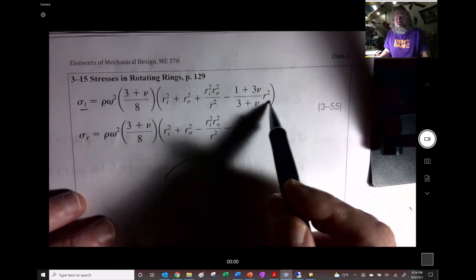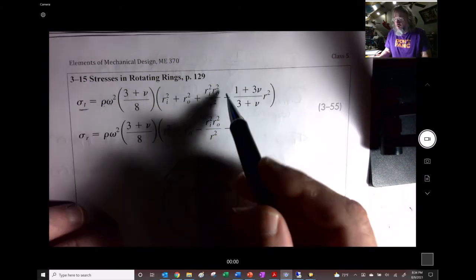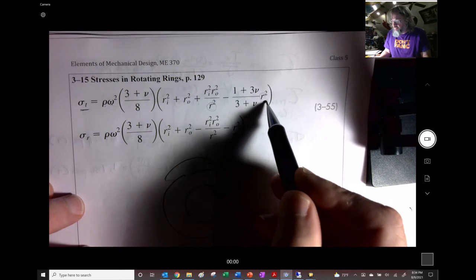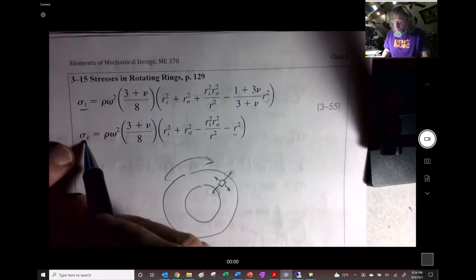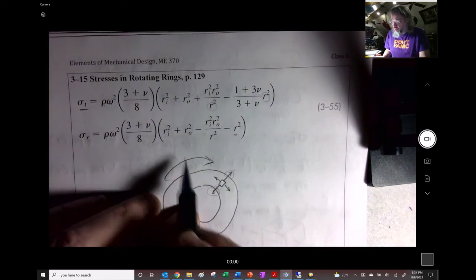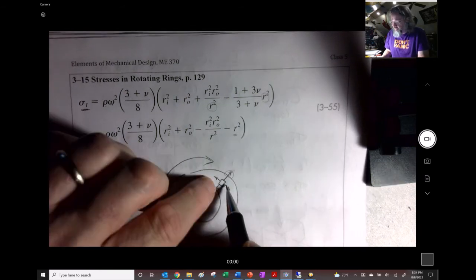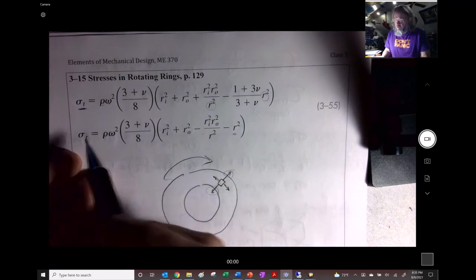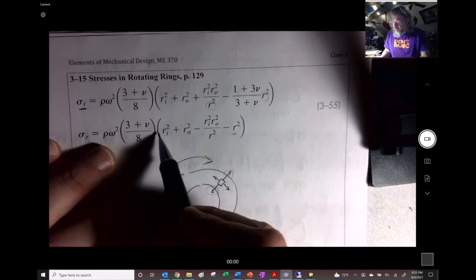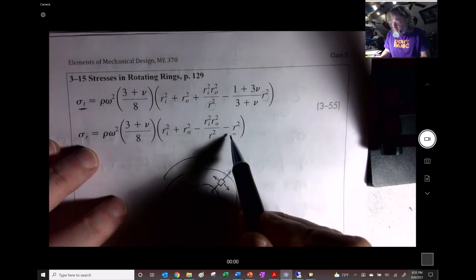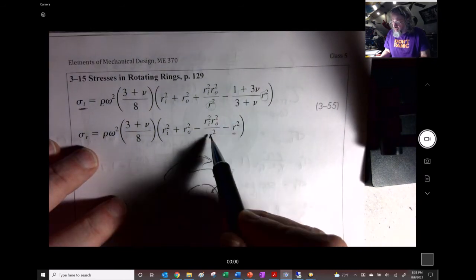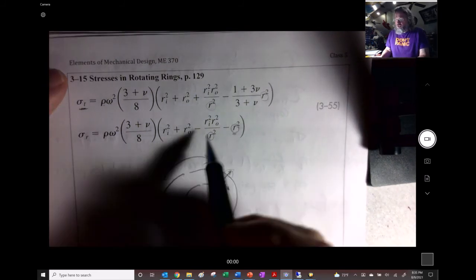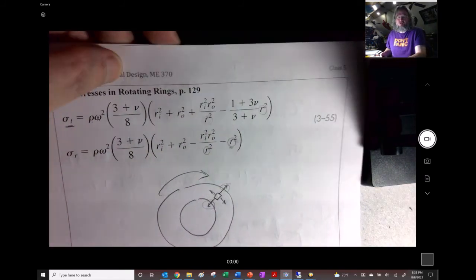This is a description of the distribution of these internal loads, which is what stress is, right? This also doesn't have a subscript right in there. Similarly, that's the hoop stress right there, that tangential, and that's the stress that's coming outwards. If you have a stress element, that's the middle of this. We also have radial stress, which has a lot of the same traits. This parameter right there and that parameter both have no subscript. So these have a similar type of distribution.